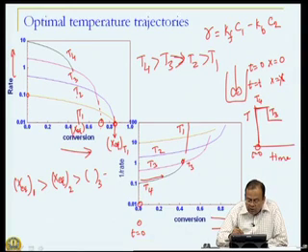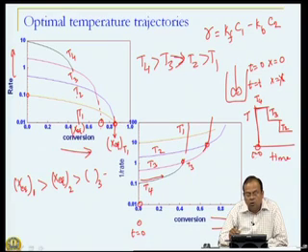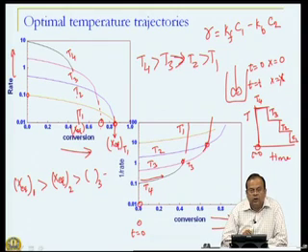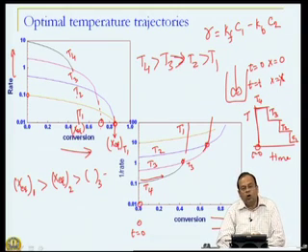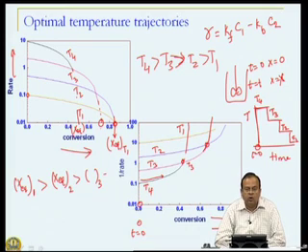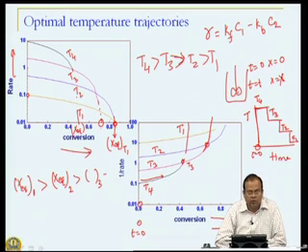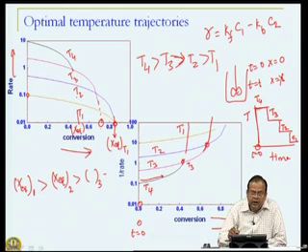But that again I cannot keep forever, because at some point this line also crosses. So, after this point I see my T2 temperature gives me lower 1 over R. That means I should reduce my temperature to T2, further reduce it to T1 and so on. So, how should I operate my batch reactor for a reversible exothermic reaction if I am trying to do it in a non isothermal manner? Keep high temperature initially, then lower the temperature, further lower the temperature.